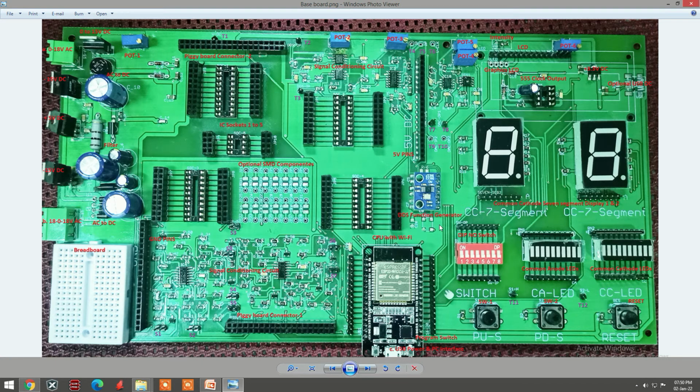Digital means here it is programmable. This function generator, a tiny IC, is interfaced to this CPU through an SPI port, the three-wire connection. So through software, you can program this function generator to generate the desired waveforms. We will discuss more about the application later. But this part is replaced by the function generator.